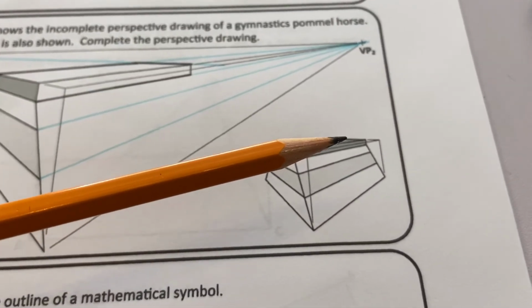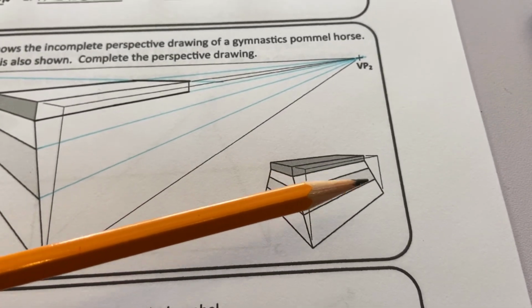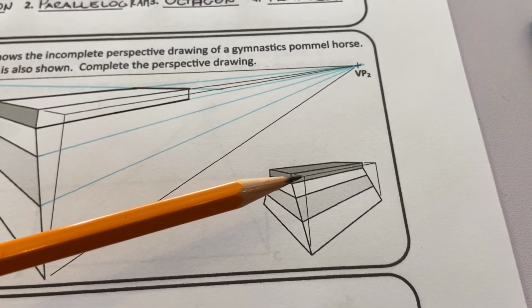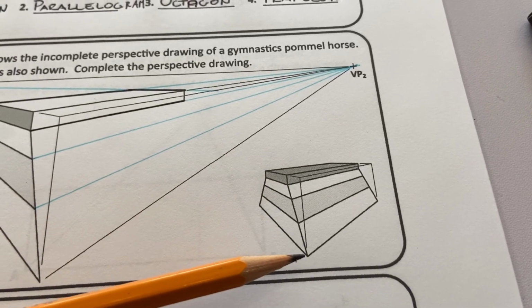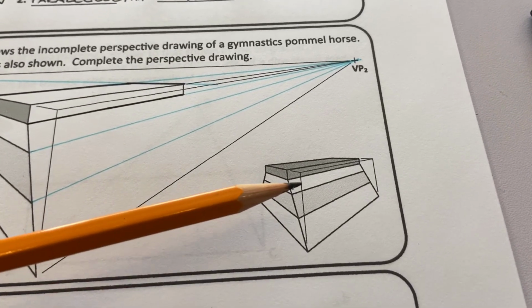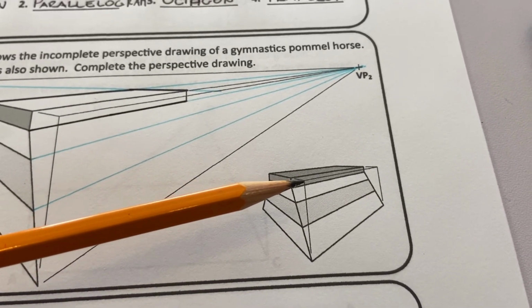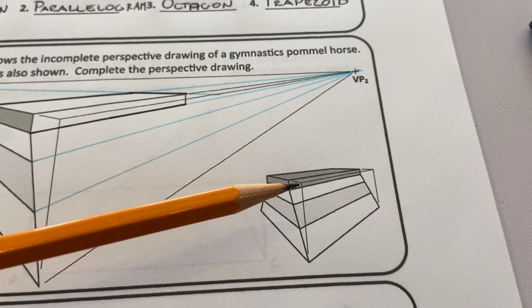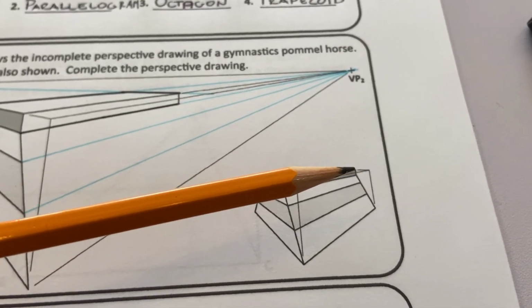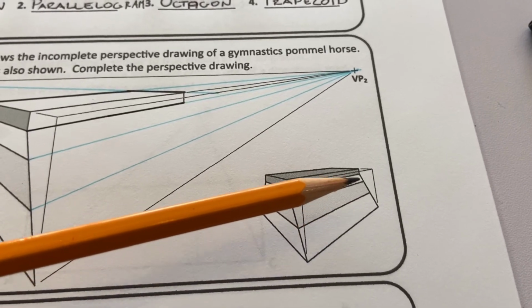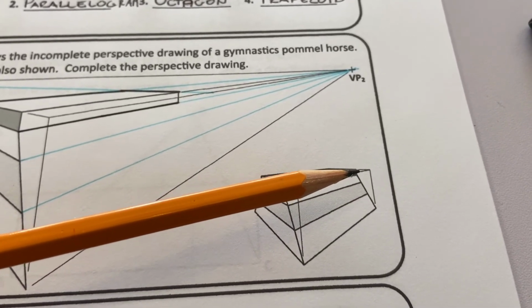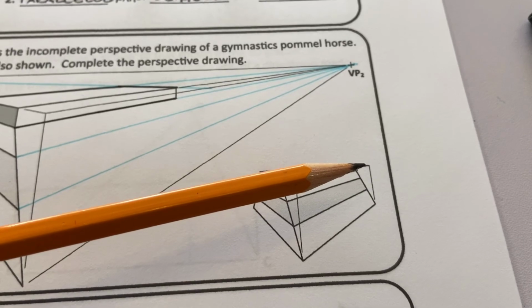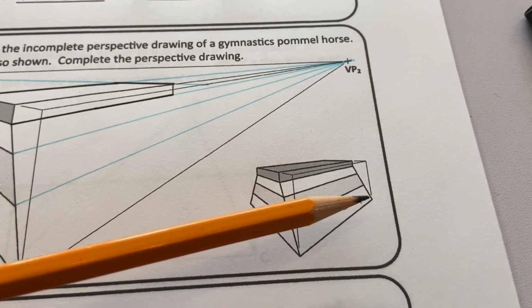And if we move over here, we can see how that point is obtained. That this external corner that we look at here, so if we bring that corner up and extend this corner back, that gives us this corner here. And if we draw that line going back to VP2, as that meets with the top line coming over here, where those 2 lines meet, we drop down a line then to locate that corner there.